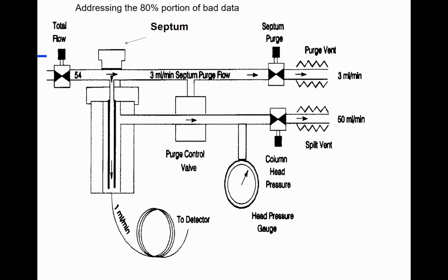Right up there. That's rubber septum. People don't necessarily look after that. We're poking holes through it all the time. And guess what? At some point it's going to leak. This is all under pressure. And so that's the first place we look. There's also a rubber O-ring up here, the seal up here. I've taken this apart sometimes and found this thing's almost dust. People just don't pay attention to the inside.